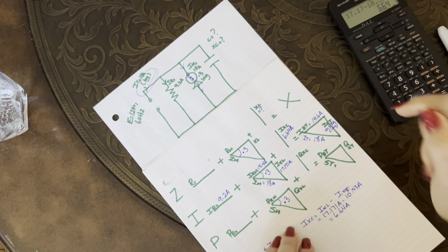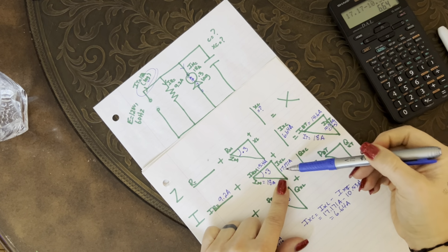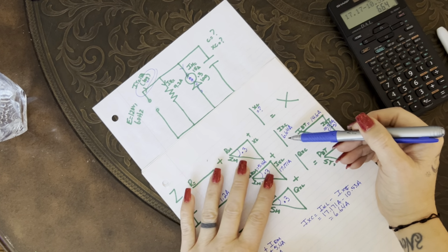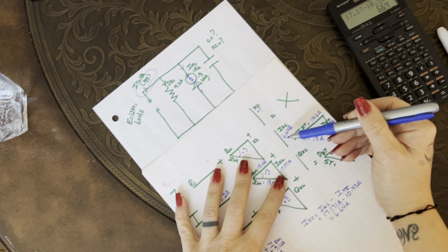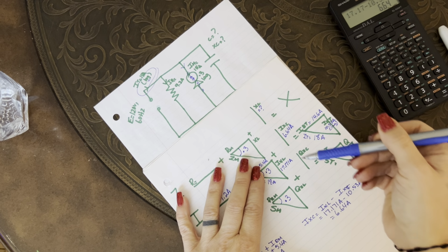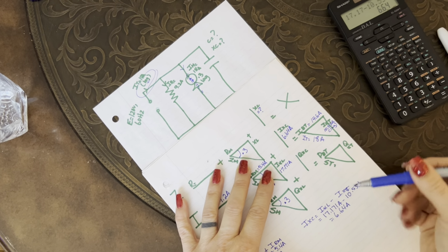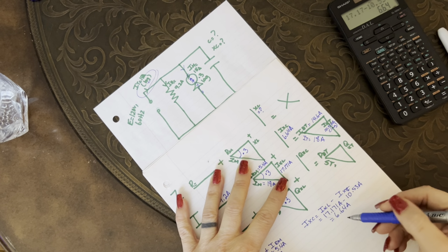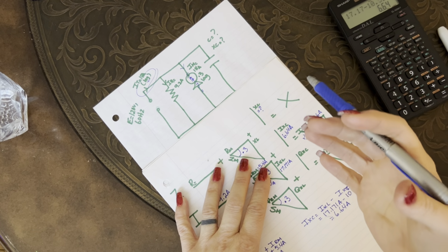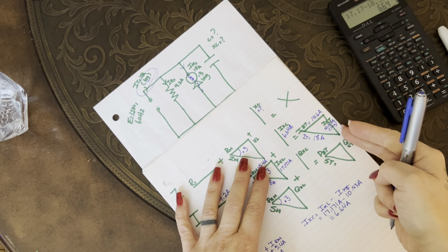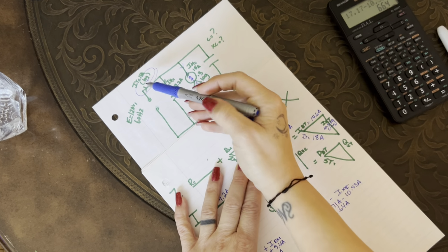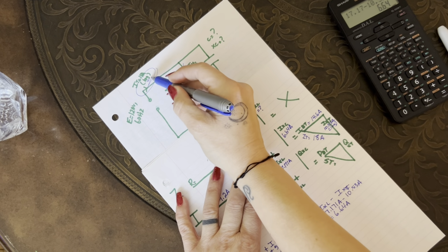So now I want you to think about that for a moment, right? So my IXL is 180 degrees out of phase with my IXC, right? So if they're 180 degrees apart, we always take the lesser from the greater for the resultant. So in this case, we're working backwards. So it's important for you to understand that in order for me to find my IXC, I would have to subtract my IXT, right? So it depends on how the circuit is built. Sometimes you're working this way towards an IXT, but in this example, we have to use the IXT and work it backwards. That's why it's super important to recognize that incoming current is lagging.